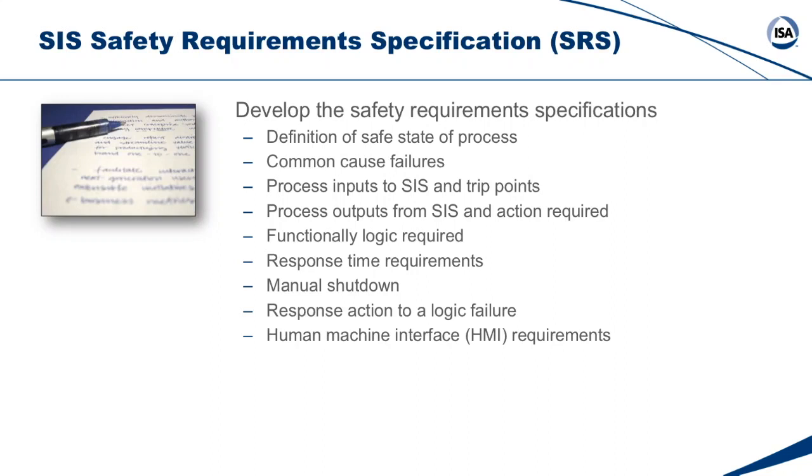Because if you have screens that are a P&ID, piping and instrument diagram representation of your process, with 40 or 50 numbers sprinkled on the screen, numbers showing flow, level, pressure, and you have red and green for pumps and valves that are on and off and open and closed, you have the world's worst HMI that will cause an accident eventually. We have learned the hard way and through plenty of industry studies what makes an effective HMI. That's a whole topic all by itself.